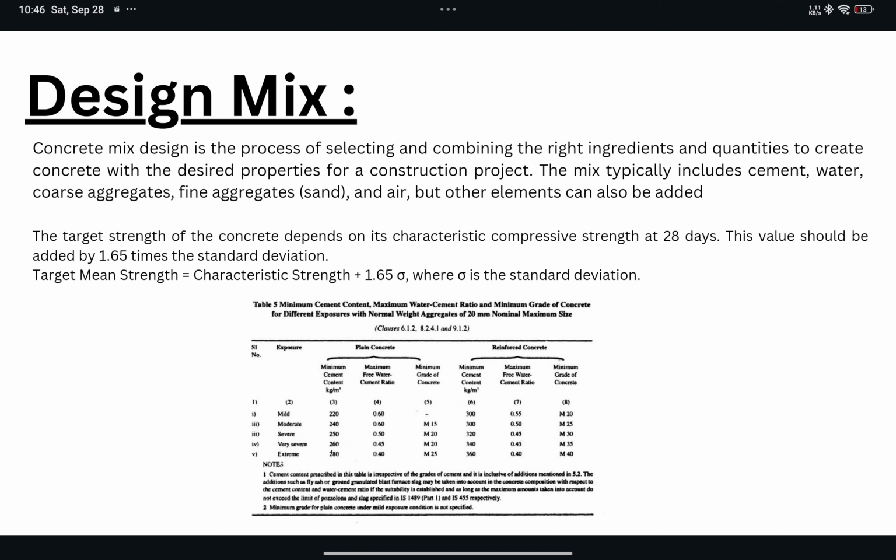In design mix we can produce it from the batching plant, but from the batching plant we can't produce a volume mix. Volume mix is for small projects where the quality control parameters are not required that much, and the cost and requirement of the project are very low, and where the material is required at a very early stage of the project, where we do some foundation of the batching plant and all those things at the starting of the project.